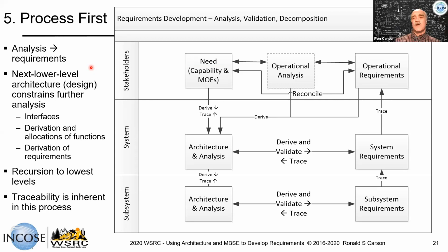Thanks. Well, I've seen the problem that if you fail to put a state definition in a requirement, sometimes it doesn't happen in the proper state, or worse, it can happen when it never should. And that can be a real problem. So the practice of identifying the applicable states for a requirement is something that should be considered, especially for a function that is supposed to be limited to, like, it only happens on the ground. For an airplane, it should never happen when you're above the ground. Well, that should be stated that way. It can only happen in the ground state. And then it has to be proved, because if it happens in the air, it can kill people. And I know an example that I won't talk about right now, but it was in the news 30 years ago. It was a very tragic accident, but it was because of a lack of state definition on a requirement. Yep. I concur. Thank you.